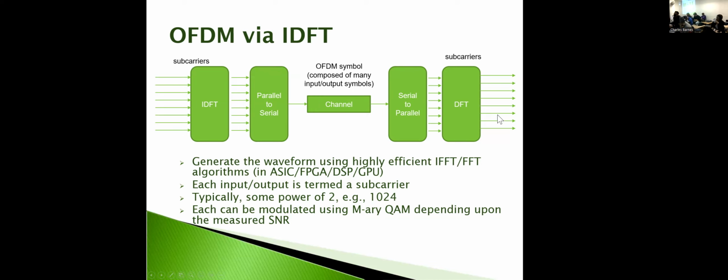Now, each of these different subcarriers is modulated using some level of, for example, M-ary QAM. And if this spread of subcarriers, and again, I've drawn 8 here, but it's more likely 1,000 or so, might cover 10, 20 or 50 megahertz of spectrum when you add it all up, the channel may vary in response over this due to fading, right?